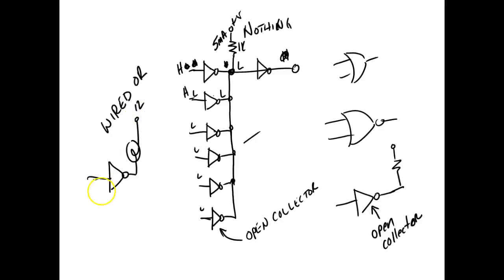Over here, we're controlling this with standard TTL logic. This chip is powered up on plus 5 volts and common, but the output is not determined by what you power the chip on. It's what's required by what that transistor right there can block. So a 7407 can actually go up to what? 30 volts. Yeah, so this would be acting like the resistor, but on a 7407, it's not determined by what you power your chip on. It's what you put across that output transistor. Y'all understand what we're saying? And a 7407 can go up to 30 volts.